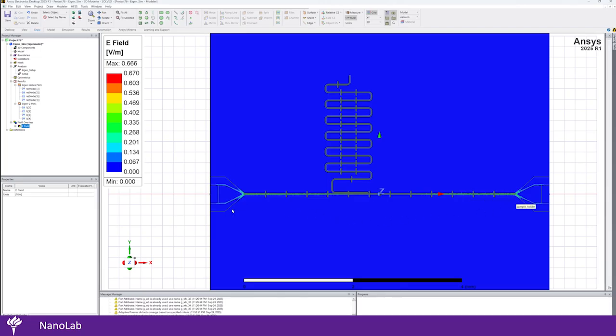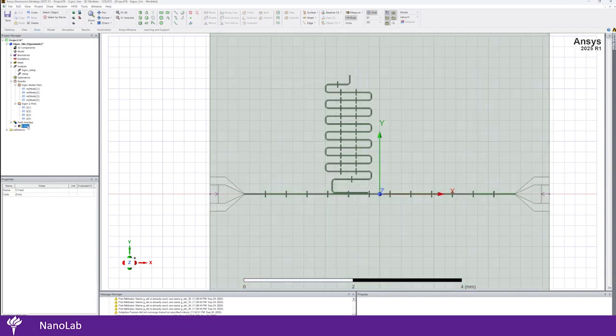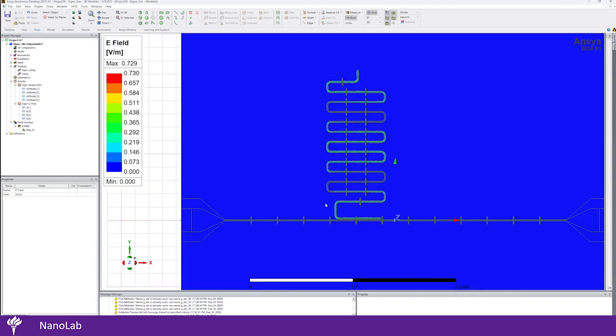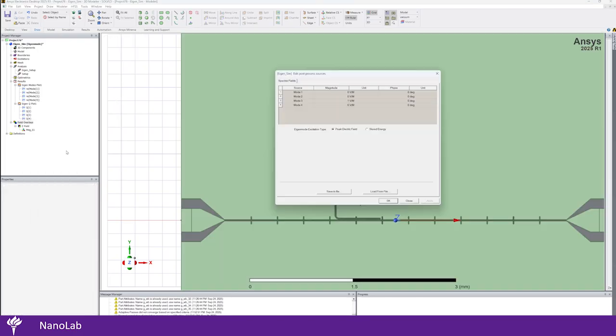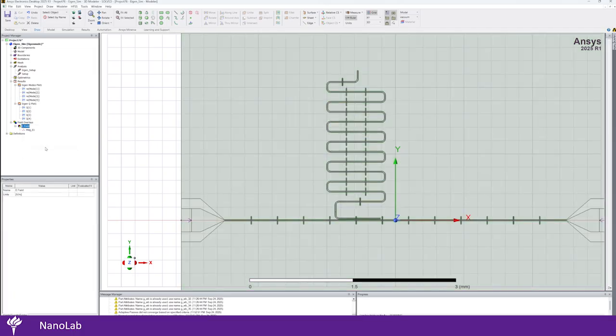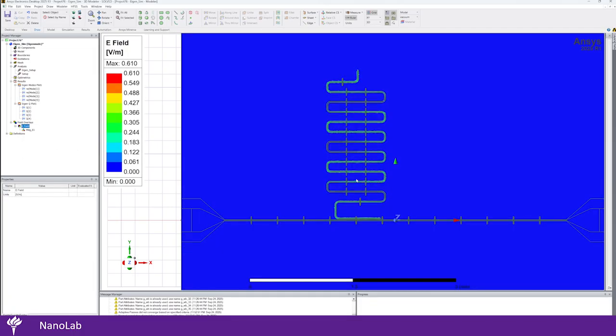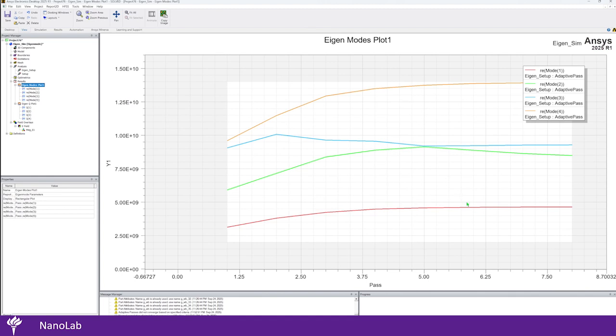Be aware of such natural frequencies and make sure they don't interfere with your desired resonance frequencies. Let's check the third mode. You can see that the resonance is coming from the second mode of propagation in the resonator. Based on previous videos, you can explain what it actually means in a half-wavelength resonator. Time for the fourth mode. The same as the third mode. The fourth mode is showing the third mode of the propagation in the resonator, which is already too high and above 10 GHz. So we can be somewhat assured that the design is free of extra and disturbing modes of frequency.